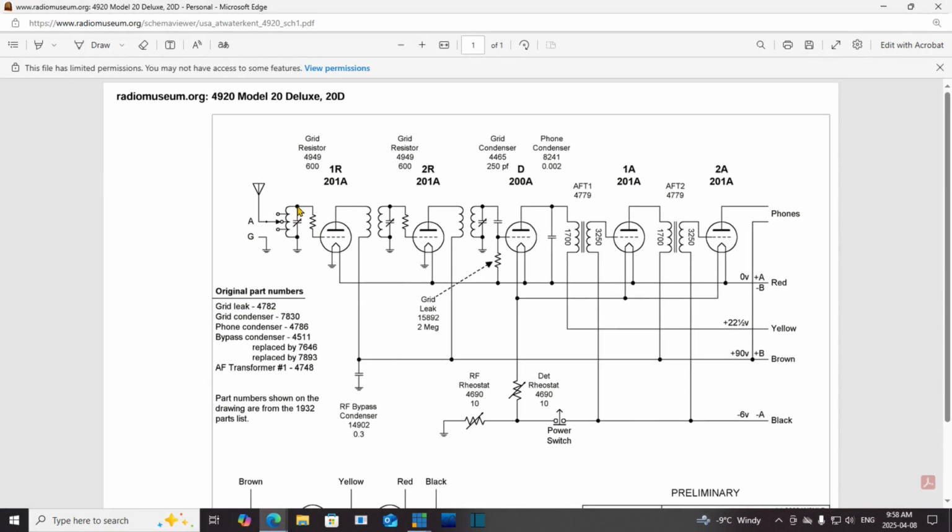Okay, let's look at the schematic and see if we can find where that is on the schematic. So there's a resistor right here. Wire wound resistor here. Is anybody telling me what the resistance is of these things? Maybe there's another one that's intact, like maybe this one. Oh, this says 2 megohms right there. But why don't you tell me about this one?